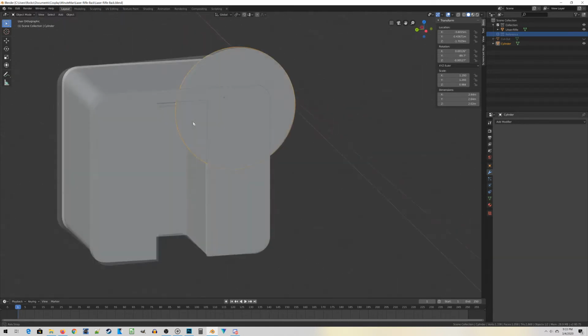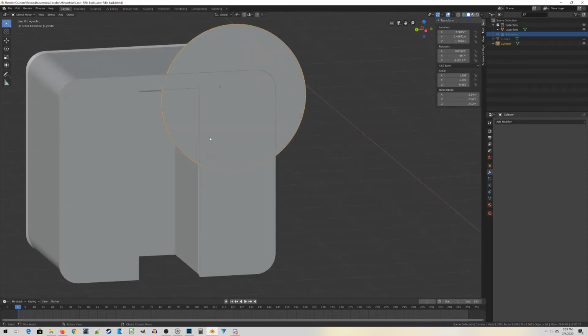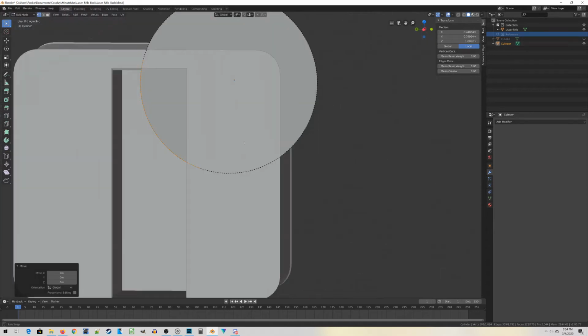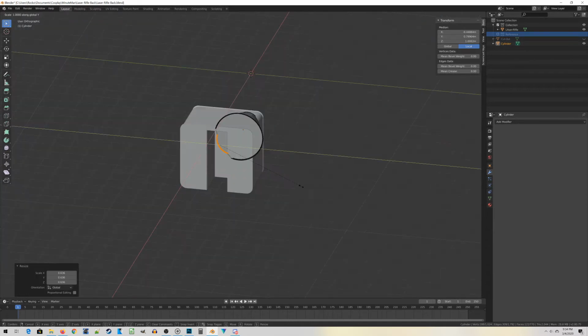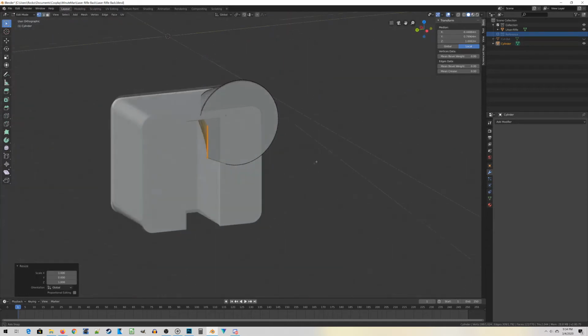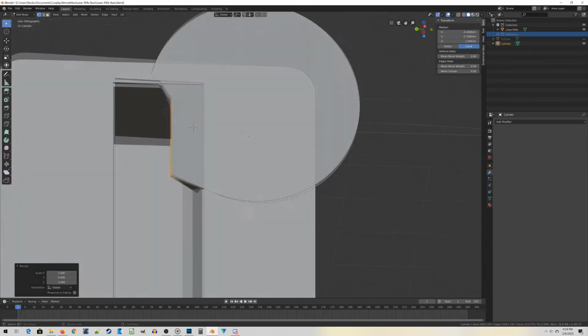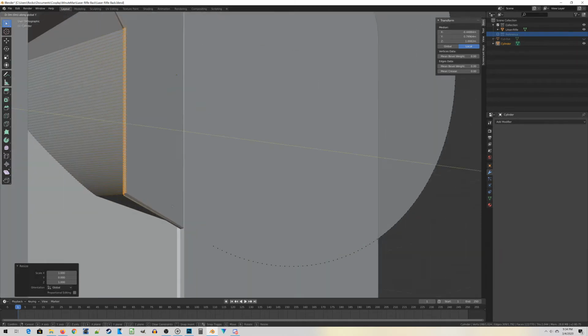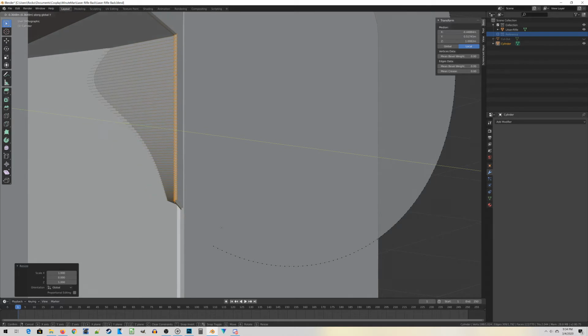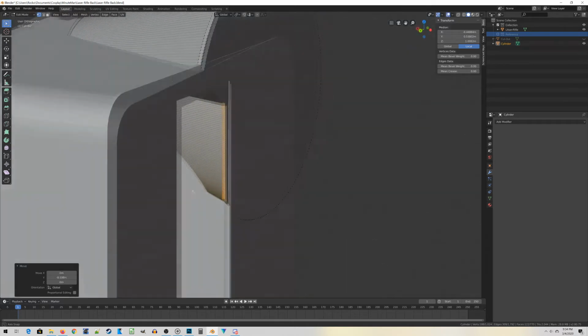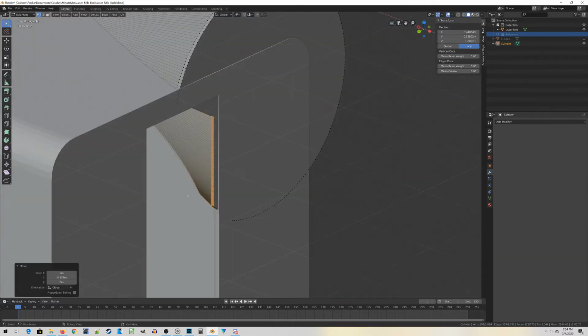But what we're going to do is just move some vertices around that are going to be hidden in the object that you're not going to see. So let me just kind of shove them somewhere and I think we'll be alright. I think that will solve the problem. I just flatten them out and then move them out of the way. Of course, to flatten those vertices, it's S for scale, the axes you want to flatten along, whether it's X, Y, Z, and then the number 0.